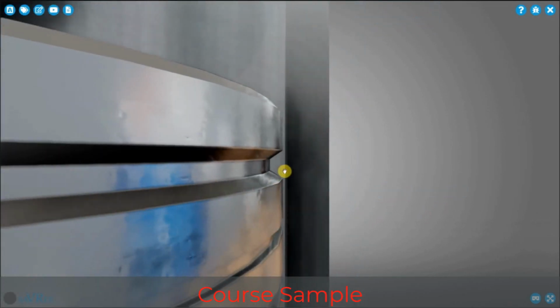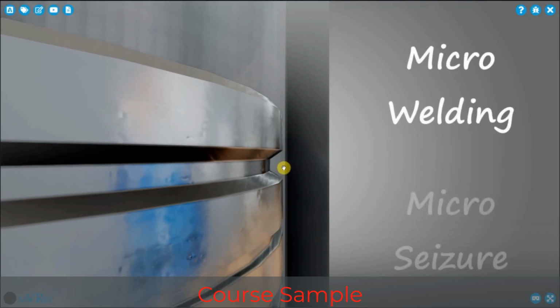cylinder. There's a very thin layer of oil between the piston rings and the cylinder liner, and we have to have that oil not just to obtain our seal, but because if we didn't have it, the piston rings would rub against the liner, we'd get micro welding, micro seizure, and the piston rings would begin to break. Not only that, but we would damage the surface of the cylinder liner.